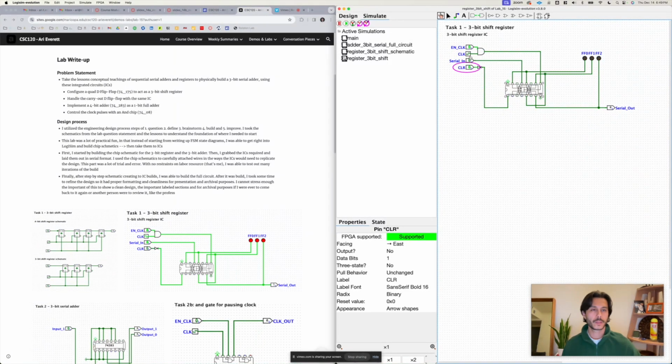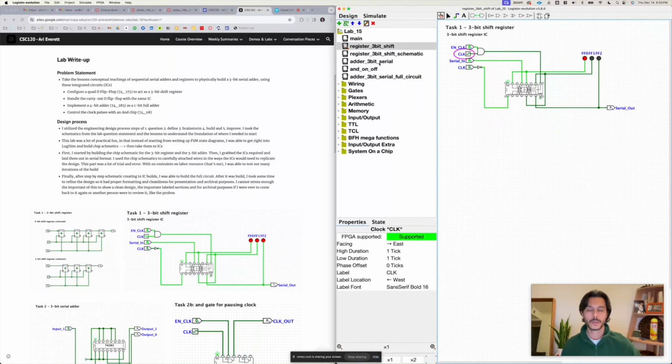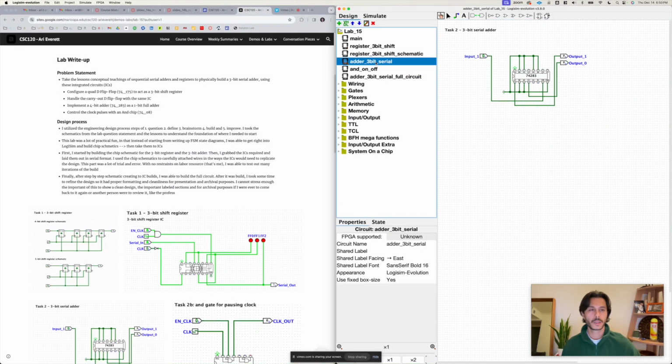So let's clear it out, and I'm going to put in, let's say, the number 100 into it, which is decimal 4. So I'd click this once, full clock cycle again, and then hit it high, and then there we go. We have 100 in there. Again, it's confusing. Remember, in serial adding, you go left to right, but the flip-flops are opposite of that, from MSB to LSB. Now let's go on to the next step, which was the serial adder.